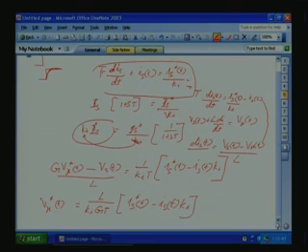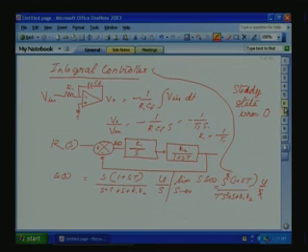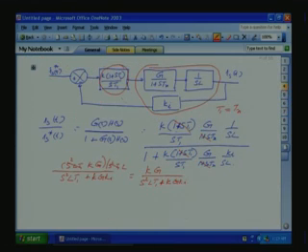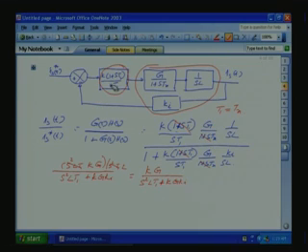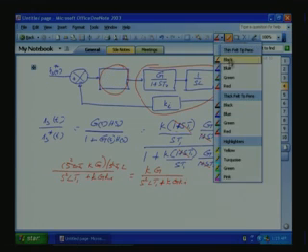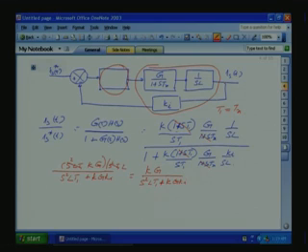So, to get the VRT star, we have to put this gain element L by Ki GT here in the closed loop controller. That means, if you go back to the controller here, instead of PI controller, we have to put a proportional controller here.